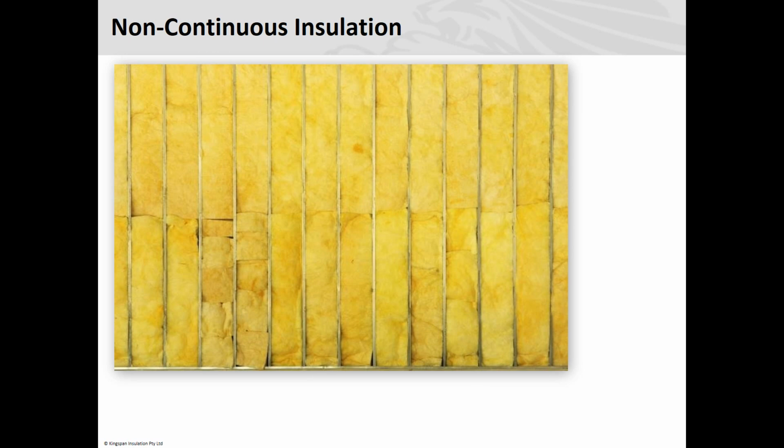What type of failures do you come across in your profession? What sort of failures do we get with insulation? Some of the failures you might get are maybe some of the foil delaminating, but you don't get too many failures in insulation. I've seen issues in houses with the sarking degrading over time. You see that hanging out in shreds in roofs. People don't complain about putting insulation in, but they don't get enough insulation, that sort of thing.